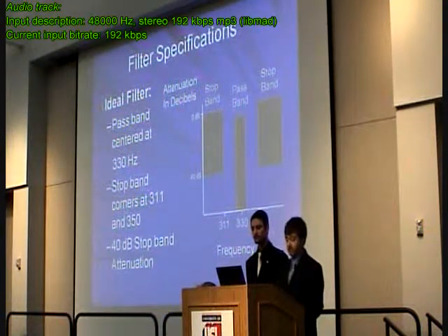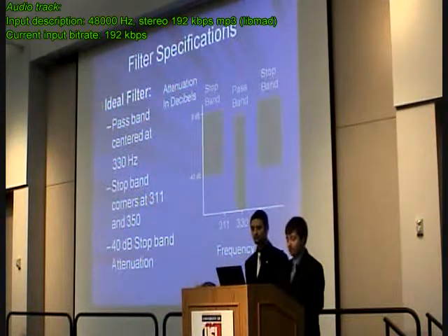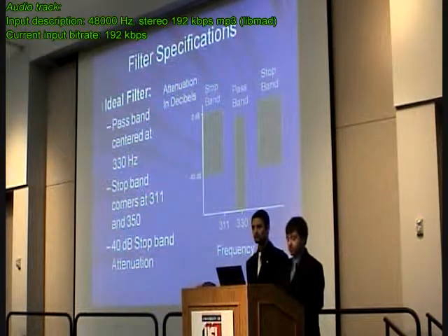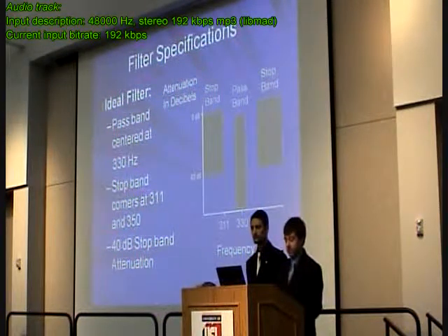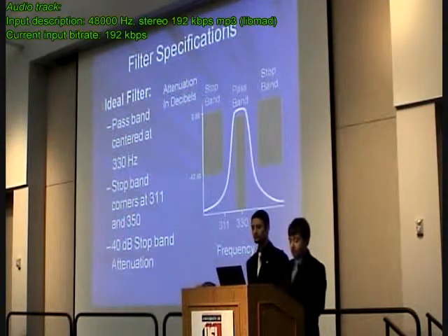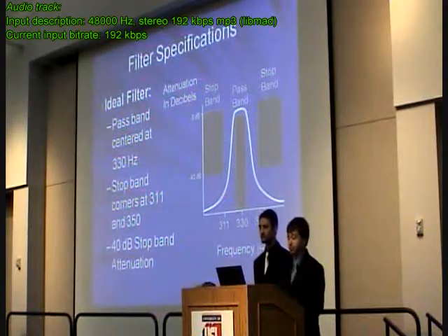For this design, these frequencies were held to a magnitude of -40 decibels, or about 1% of their original magnitudes. Other frequencies' magnitudes will increase as they approach the central frequency of 330 Hz. The white line shown shows the desired shape of the frequency response of our filter.